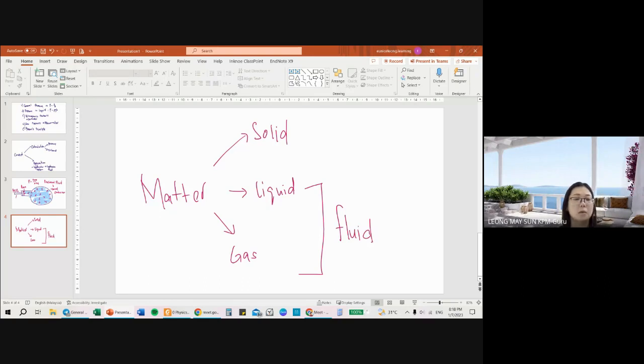All right. So does this mean that Pascal's principle is applicable for gas, for vapor? Yes, it does, as long as it's an enclosed fluid. For example, even a balloon. If it's a balloon, it's in an enclosed system, so the air cannot go out, and if you exert a force onto a certain area, pressure is transmitted equally. But for Pascal's principle in SPM, we usually focus more on liquid.